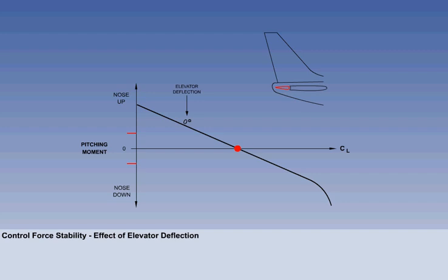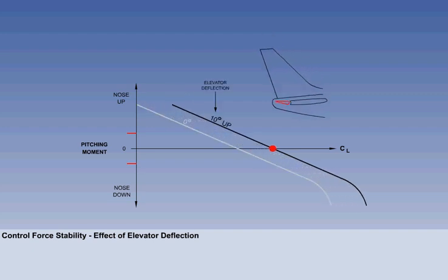The illustration shows a certain amount of static longitudinal stability, with the elevator at neutral. The aircraft is maintaining level flight by increasing the angle of attack as the indicated airspeed is decreased, until once again it is in equilibrium at a lower airspeed. To hold this angle of attack at a lower airspeed, the elevator must remain displaced at a position 10 degrees